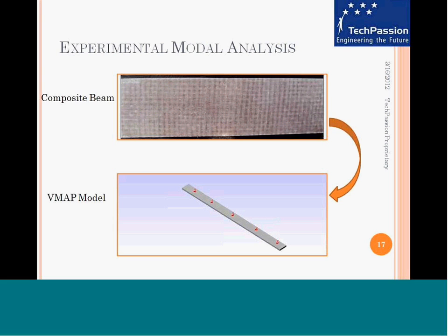Now, it could get really complex depending on the number of layers that we are using, and since composites can give you a lot of advantage owing to their tunable directional properties, you could leverage them and make an interesting composite structure with multiple layers and the angles in them placed in different directions instead of being parallel as what we saw in the simulation. When the structure gets as complex as that, again, it's more important to understand how do you model damping really?